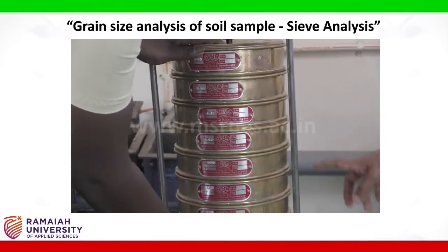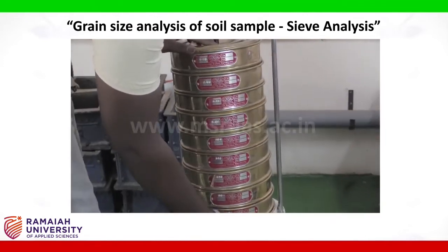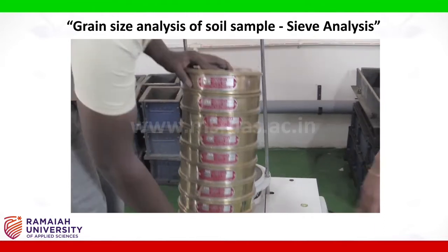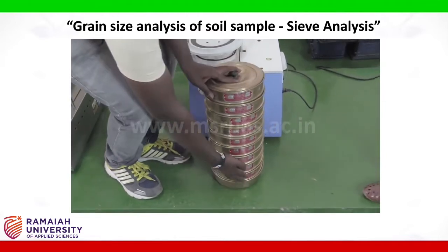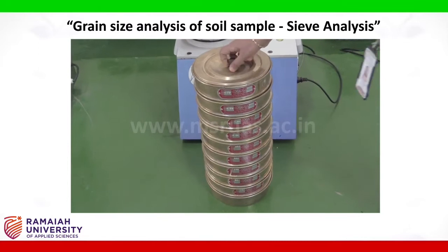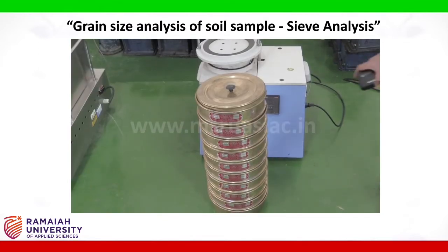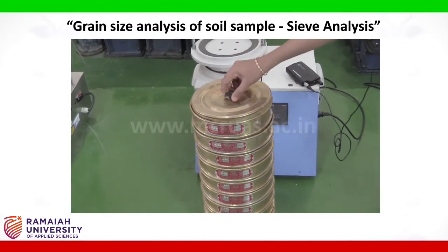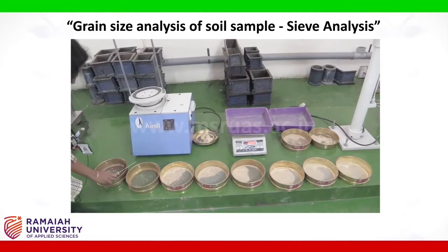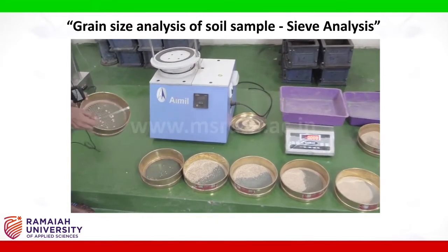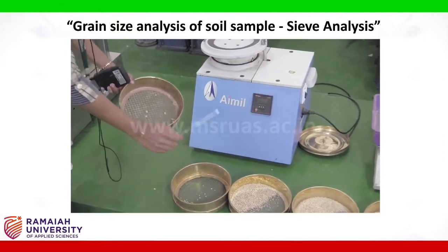Remove the sieves from the shaker. Once the sieving is over, weigh the soil sample retained in each of the sieves.